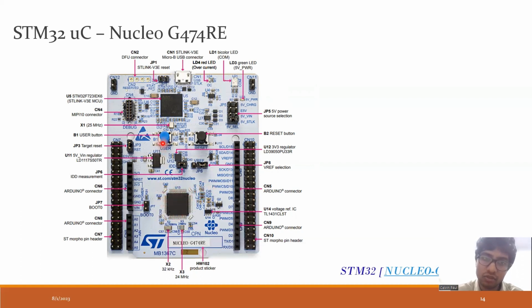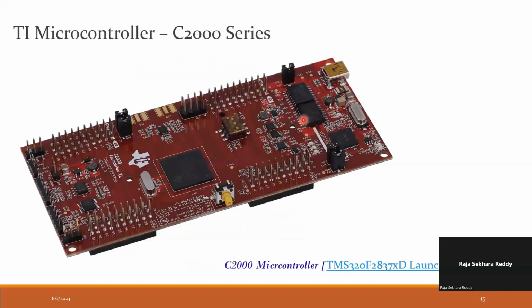And these are some push buttons also. This is a reset button which will reset it back to default. Like a restart button in our PC, there is a reset button in this microcontroller kit. Also, there is this IC which is used to dump the code over here. And over here, we connect the USB connector to our laptop. What is there in the laptop is my software, in which I write the code. Using this USB cable, I will dump the code into this microcontroller via this IC. So all this is there, and the various other stuff we can check.